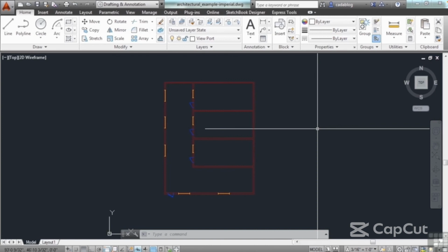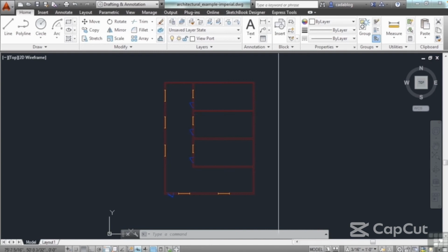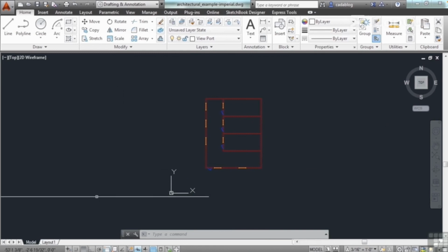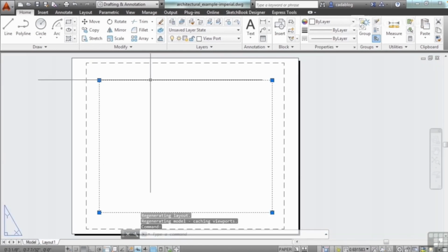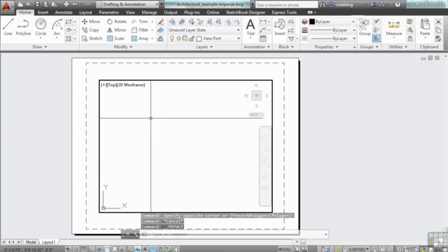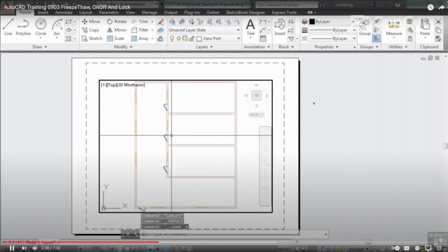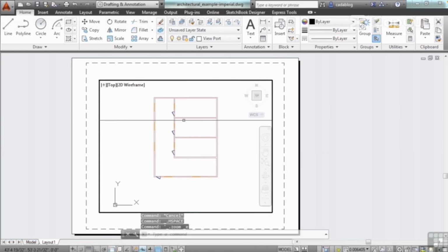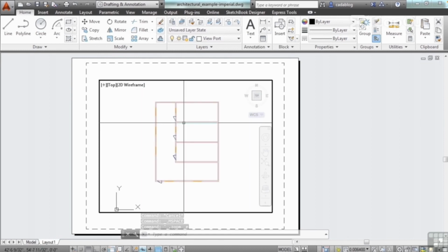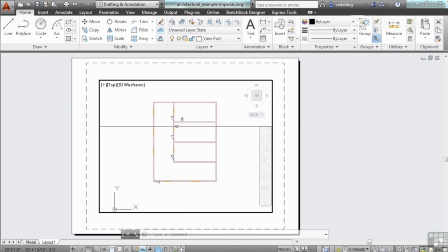And ever since Paperspace was introduced way back in AutoCAD 11, we're on version I think 28 or 29 now, with 2013, the freezing gave you more options in the viewports, and we'll talk about those. In a layout or in Paperspace, which is down on the tab down here, this is a viewport. And in this viewport, you can double click and that will activate it. Do a zoom extents and you can see your object right here.